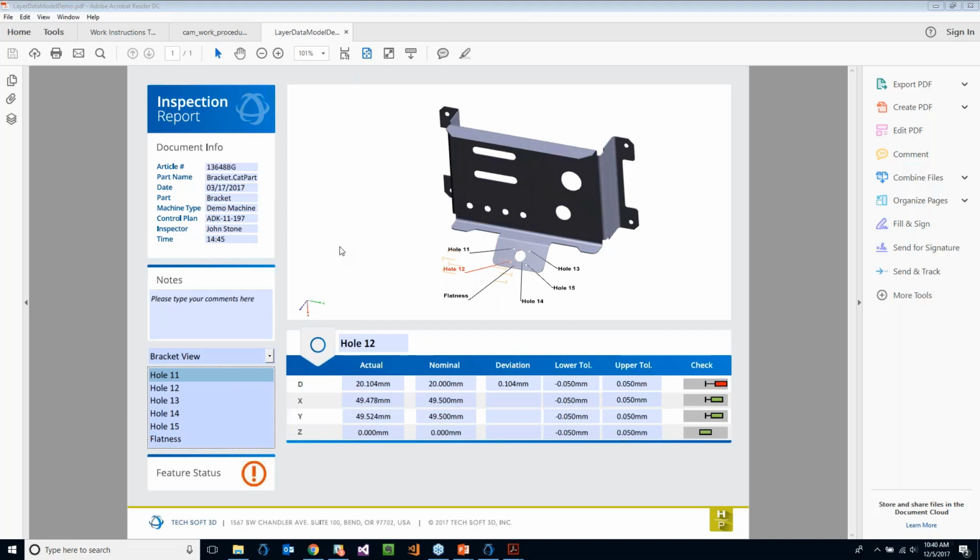Let's see, another question. Do you provide access? Oh, no, I'm sorry. We just answered that one. Are you able to dimension in the PDF or generate dimensions for the 3D model from the API? Yeah, there's lots of ways of doing that. There is a dimensioning tool in Acrobat that allows you to take measurements on your data. Also within Hoops Visualize, we have a set of tools that allow you to add dimensions there as well by clicking on edges, point-to-point, circular arcs, a general set of dimensioning tools, and then also using our APIs if there's very specific things, kind of obscure dimensions that you want access to, those can be built out just because it is an API and we build applications with them.